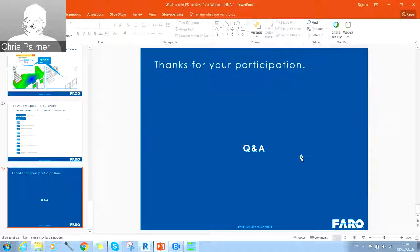Yeah, hopefully that was covered during the presentation, but just to recap, obviously we are only working with what's visible. So if we have a pipe that's got insulation on it and we've scanned that, we are working to the outer diameter. So we can specify the insulation radius and the size and things like that, but that's not intuitive, in terms of it can't see through the insulation to the pipe. It is just a case of using your engineering knowledge to determine what that should be. Which is really the case if you were modeling it in any other way as well. There's no real way to test that unless you either know or you manually check it.